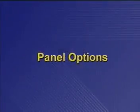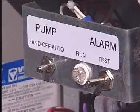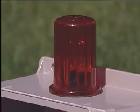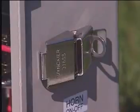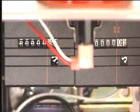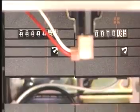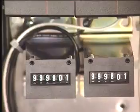Options you might want to consider for your effluent control panel include switches for hand-off automatic control, high and low level alarms, pump run indicators, lockable latches, cycle counters, and elapsed time meters. Elapsed time meters and cycle counters are especially useful in diagnosing problems in the operation and maintenance of systems.